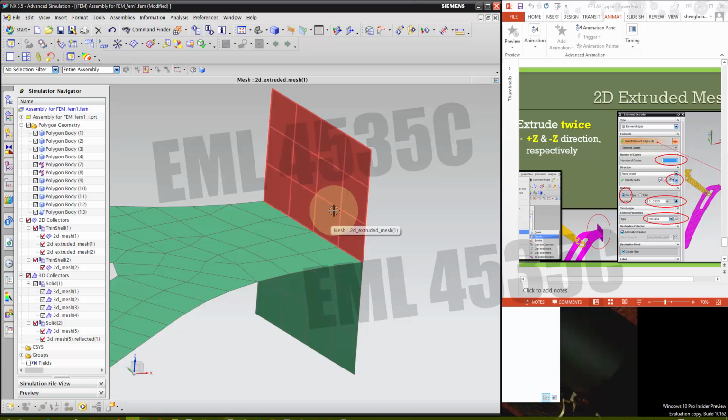You don't have extra nodes. This piece is sharing nodes with the other pieces on this edge. So the principle is if you share a node, NX will consider this as one piece, a solid piece. So these three actually are just a continuous single piece.